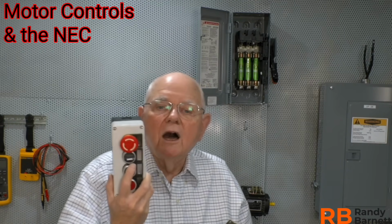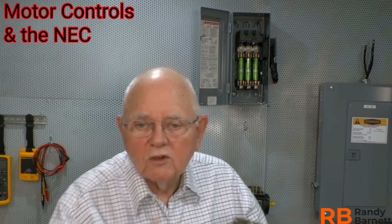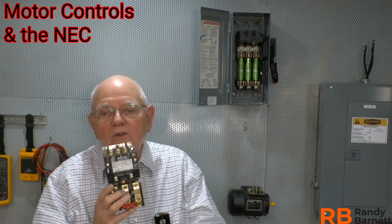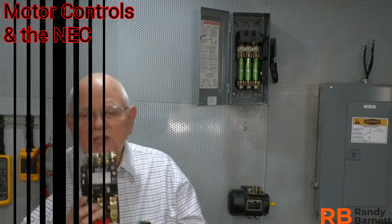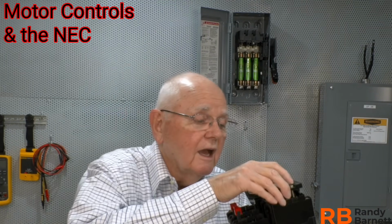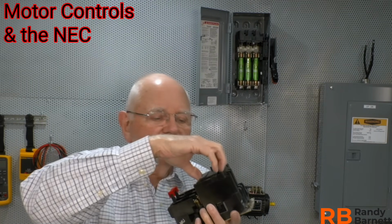Quite often what we're going to find out in the field is what? 120 volts AC. So when I buy my motor starter, I can specify what type of coil, what voltage rating coil I want in there. Let's take a look at that coil on the inside and see how easy it is to change out. I've loosened these two screws on the front on the nameplate. I pull off the nameplate. There's my coil. So I'll go ahead and pull out the coil and show it to you.